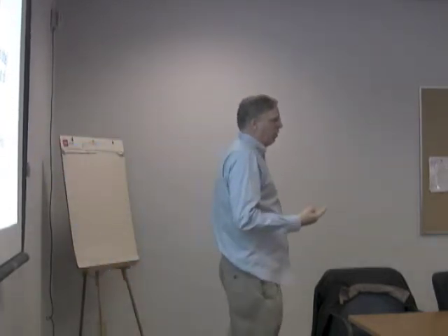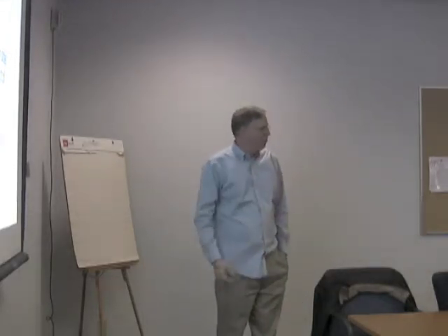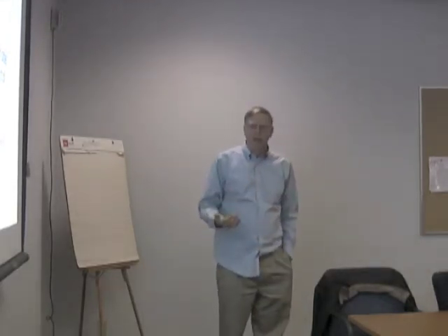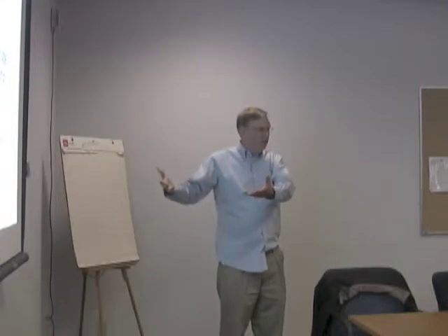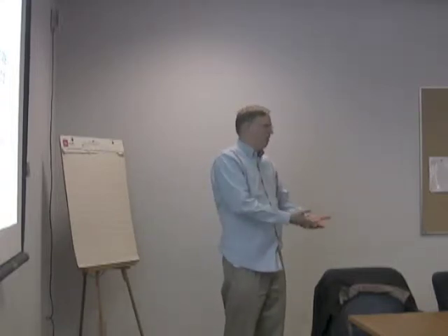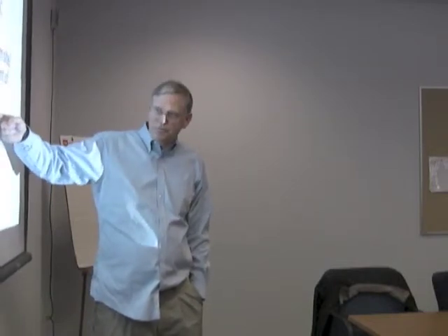So the key improvements are really going to come from site- and source-specific ground motion models, not another round of updating the worldwide models. We'll keep doing that, and they'll have another range, but that's really not going to get at our fundamental issue, and that is we're taking a model for an average site condition and earthquake condition around the world and saying our site is that. So the way you can get at this is site-specific ground motion models for path terms, or site-specific ground motion models.